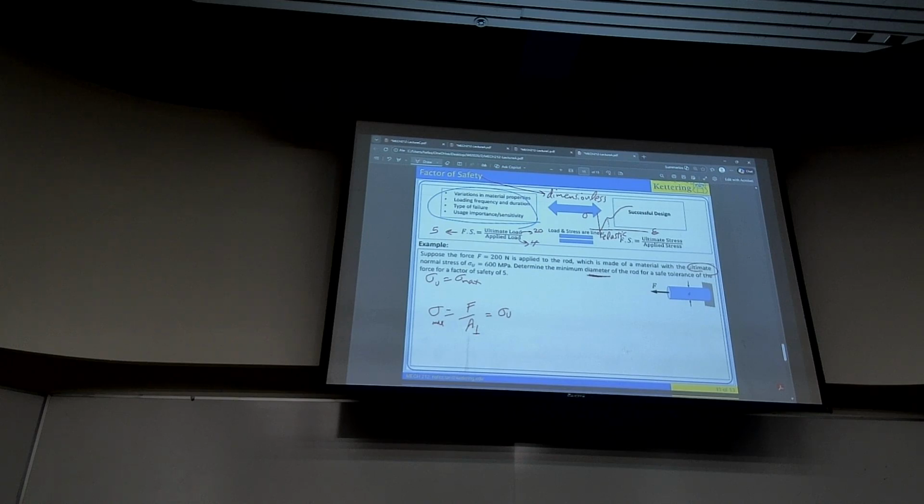That's it. So from this point on, the shortcut is this. If you see a factor of safety other than 1, divide the strength value by that and cross out that factor of safety statement. Solve it without that. As easy as that. So that's the shortcut, keep that in mind. So let's solve that.